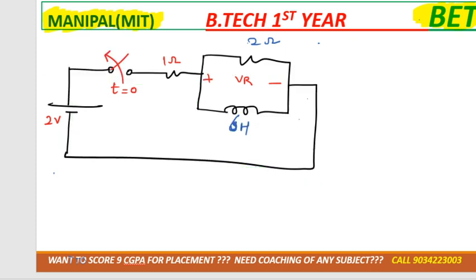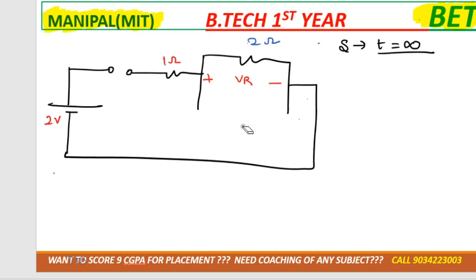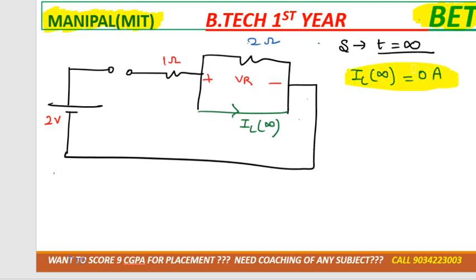Now step number 2, we have to draw the circuit at t equal to infinity. So at t equal to 0, the switch is opened or closed? At t equal to 0, it's opened. So t equal to infinity is also opened. And inductor will behave again as short circuit, and here the current would be IL of infinity. So we need to calculate IL of infinity, that would be equal to 0 ampere. As you can see, it's an open circuit, so no current will flow over there. So finally and easily we'll get it as IL of infinity 0 ampere.